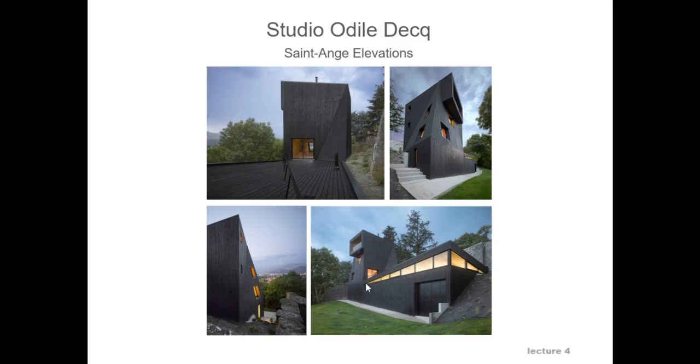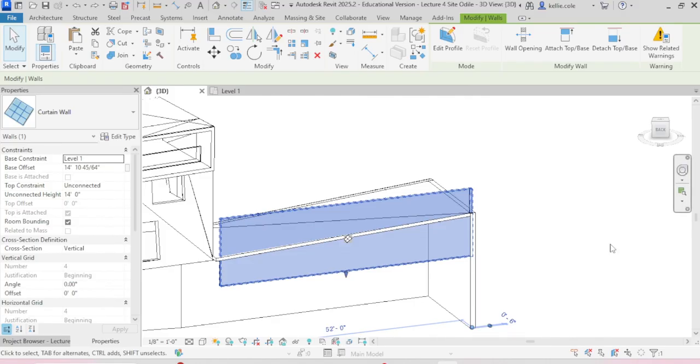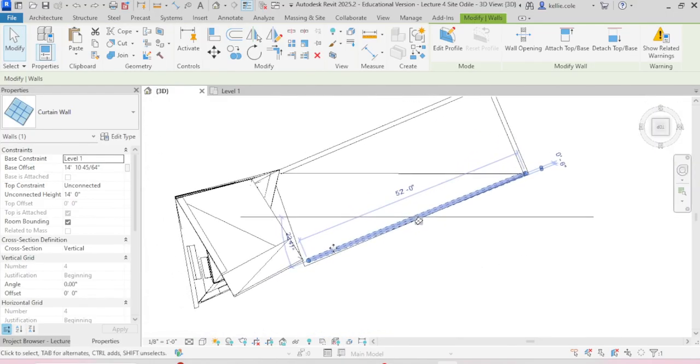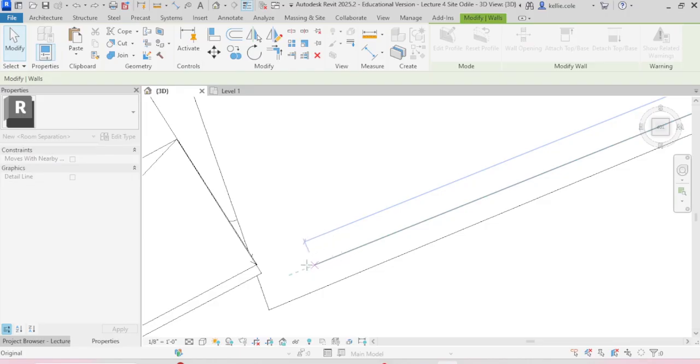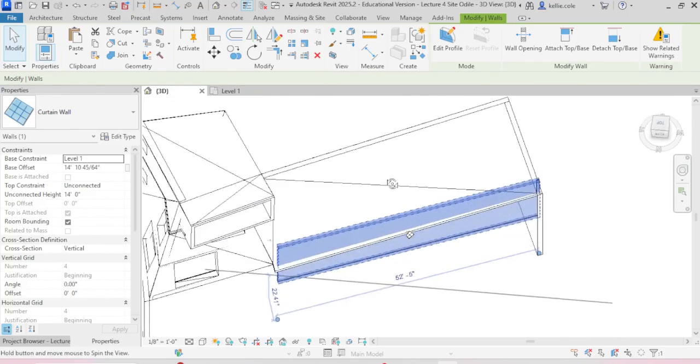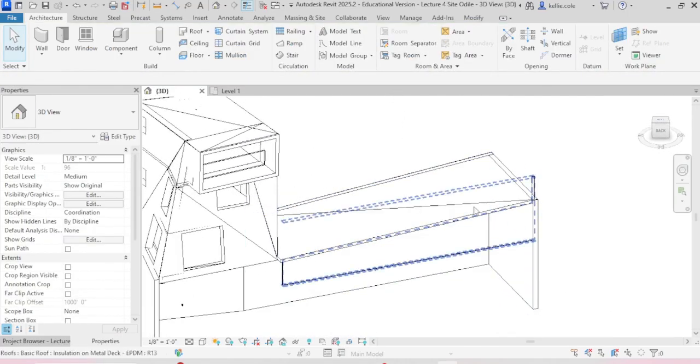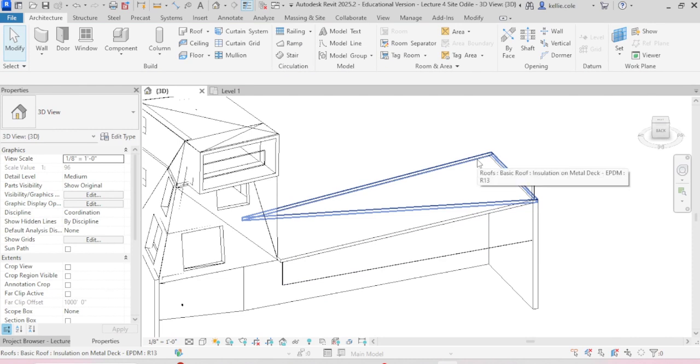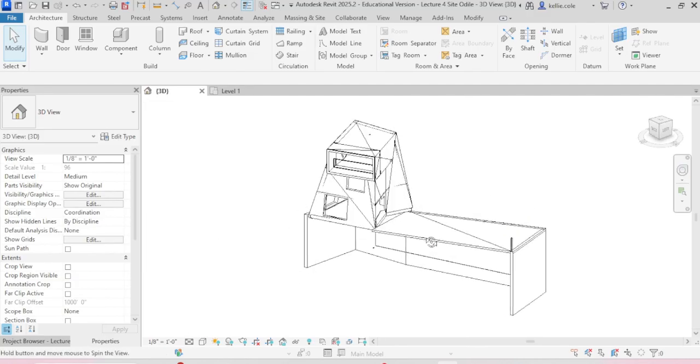It looks like that point begins near level 3. In order to shorten the wall, I simply selected the curtain wall, touched the top button of my cube, and used the endpoint to drag it into the 2-story space. If when you connect this curtain wall to the roof, there's a part of the wall that's lifting up, it could be that we need to connect it to the second plane of roof, but why don't we correct the curtain wall on this right side of the figure before we do that?